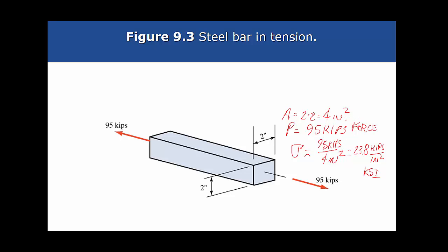This is the area, and then the stress is force divided by area. Stress, that is the density, yeah? Stress? Kind of density. No. Force per unit area. Force per unit area for pressure. Pressure is a force per unit area, yes, definition of pressure. We're not talking about pressure. This is stress. This has nothing to do with pressure, like a pressure vessel or anything like that. No. We're talking about tensile stress right now.